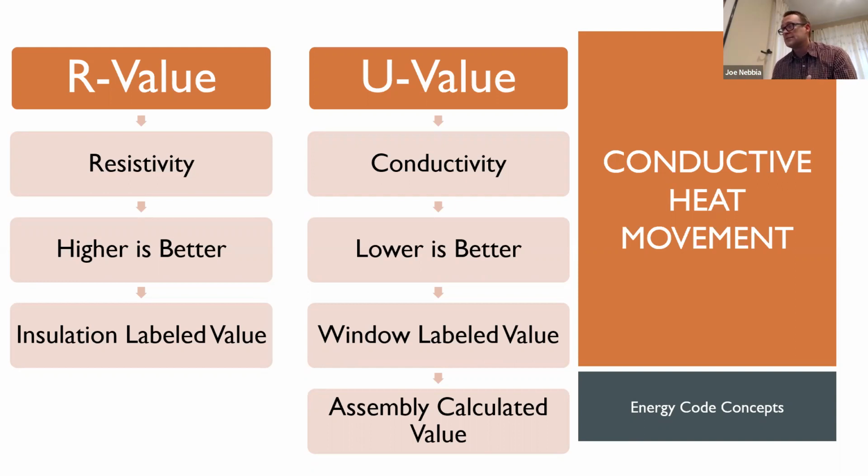That's really nonsense, because the R-value is just a conductive heat measurement. It doesn't have anything to do with the air sealing. Now, that insulation is doing two jobs at once if it's air sealing and stopping conductive heat flow, and that's good.